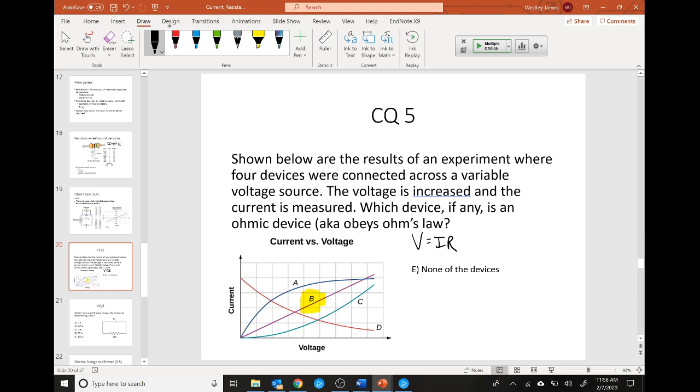So you no longer get this flat line, so at some high temperature, the current will actually start to decrease. And this is actually what your fuse does. As you are applying a voltage, at some point it gets so hot that a fuse will break. Fuses are specifically designed so that at a certain current, they reach a certain temperature. At that temperature, the material melts. It melts, your circuit breaks, it protects all the other equipment, because it's much cheaper to replace a 20-cent fuse than it is to replace a $1,000 whatever it's connected to.